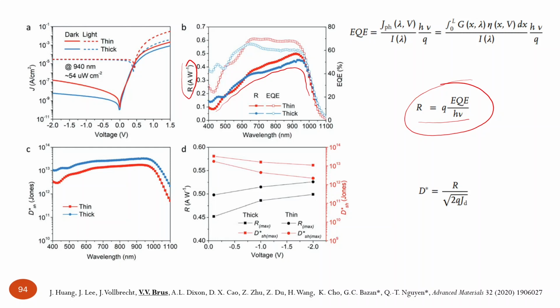So it literally tells us at given wavelengths, let's say we pick some wavelength of, I don't know, 900 nanometers, what photocurrent will be measured with such a diode at 1 watt power of monochromatic illumination hitting this photodiode, at the wavelength 900 nanometers or any other wavelength which you pick within the spectral range of photosensitivity of this solar cell. So obviously it cannot be wider than the EQE spectra because we calculated it from EQE, but it tells us in terms of electric current how much we will get when we shine on this photodiode with monochromatic light of given wavelength and some given power.